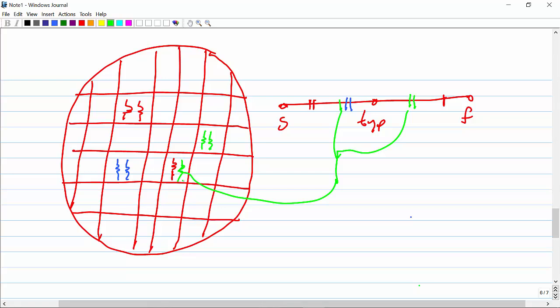So there are two types of process variation. One is the process variation inside the IC, which we call the mismatch, and the other is the process variation between the ICs. It is not inside the IC, it is between one sample and another sample, and that we call the process variation.